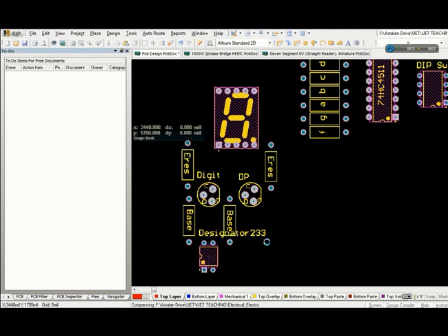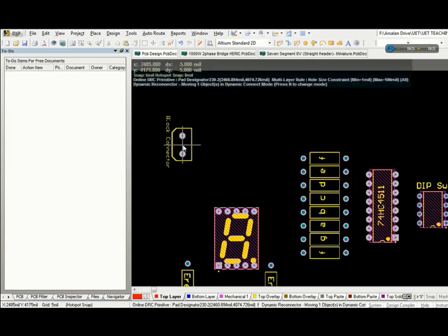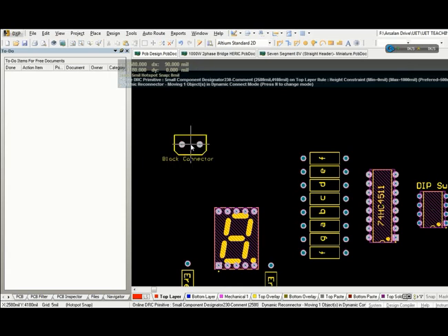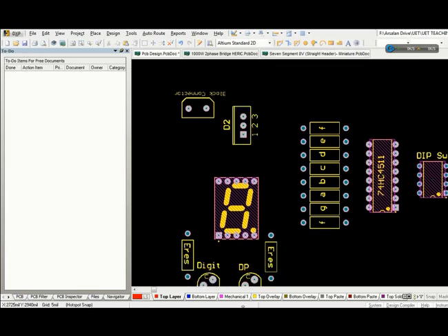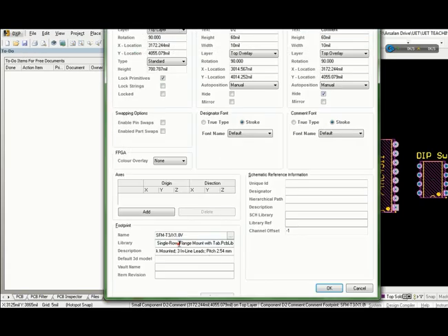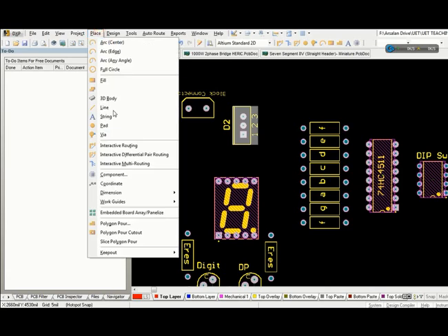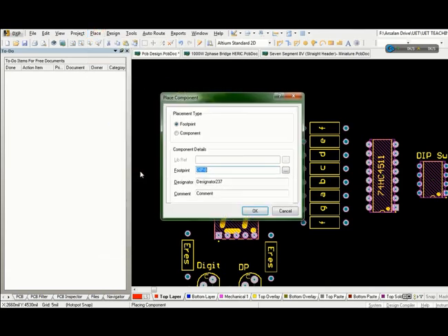You can see this is that block connector, and this time I am only using one block connector. One block connector means it has one pin for VCC and the other pin for the ground. One very important thing: what I am using is the TO220 packaging for the 7805 over here. I have copied this, and I am going to show you from place components.